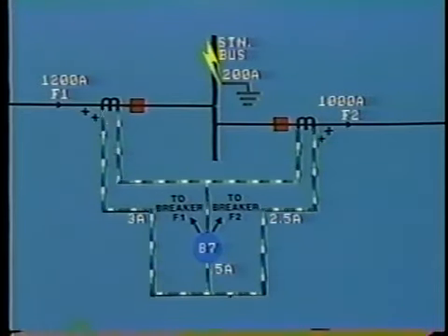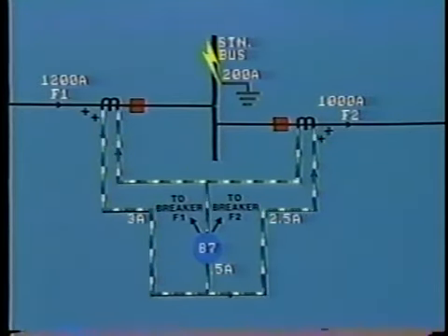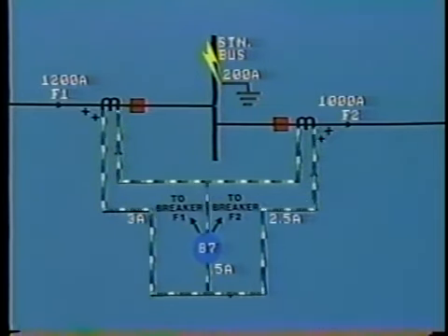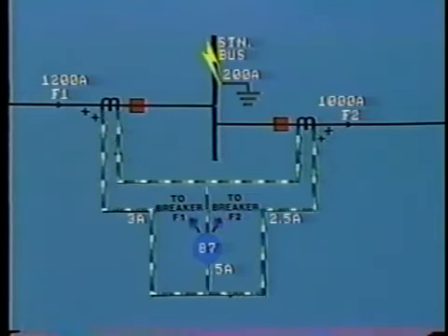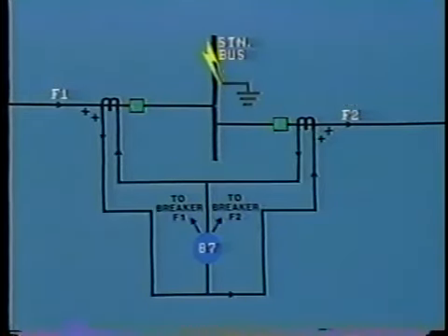Typically, differential relays are set to trip for a pickup current from as low as 0.14 amps and up to 3 amps. The tripping circuit would then open all breakers connected to the bus, in this case on feeders F1 and F2. So you can see that the relay is quite sensitive and can be made to trip for even a modest out-of-balance current.